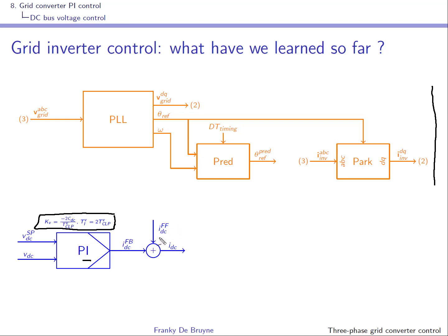If there is a current that is going to be injected on the DC bus, and if it can be derived directly by measurement or indirectly by computation, you should use it for feed forward. In our simulation exercise, we do not have such a signal, so we can forget it.